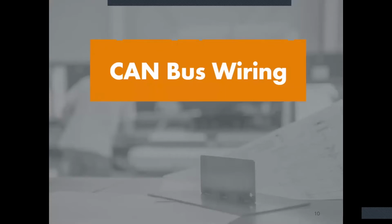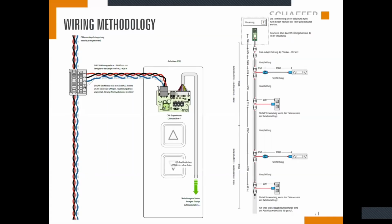I'll show you how our components are connected to the bus. There are two main kinds of wiring technologies that we use. So one is where we use a kind of ring wiring system. So these four cables, the blue and white are the CAN high and CAN low, and red and black are plus and minus, so the power supply.